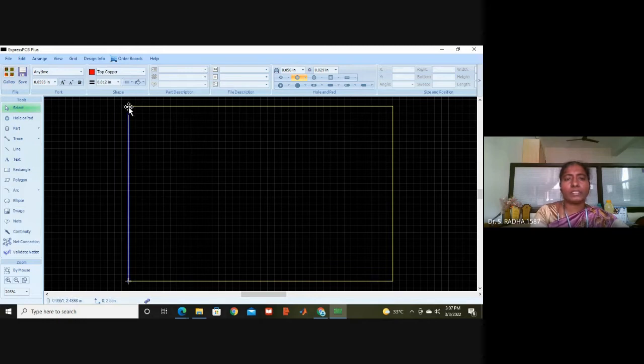And at the four ends of this yellow color box, once the entire design is completed, we want some stand screwing process. The terminology is screw mounting. So this hole or pad is used for the screw mounting. Once we put the entire design, we want to place it somewhere. If there are four stands, it will be easy. For that screw mounting, these pads are required. You can take it and put it on any PCB design at the four corners.